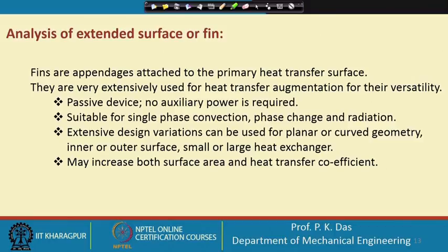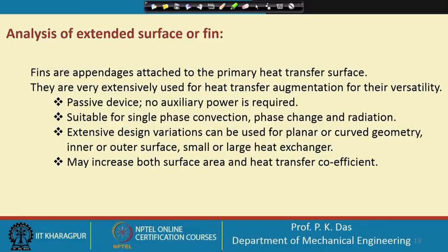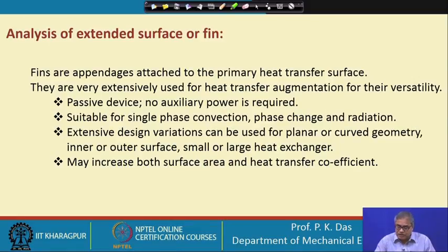Now, if we see the attributes of an extended surface or fin, which is a conductive convective surface, I will explain this term. This is a passive device, no auxiliary power is required, suitable for single phase convection, phase change heat transfer, and radiation. Even in some phase change energy storage systems, these fins are used.